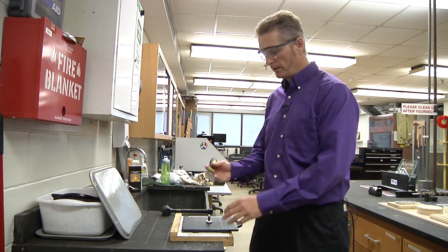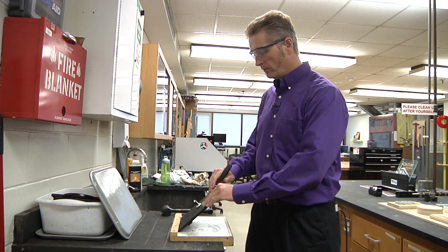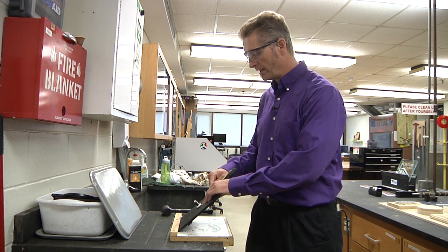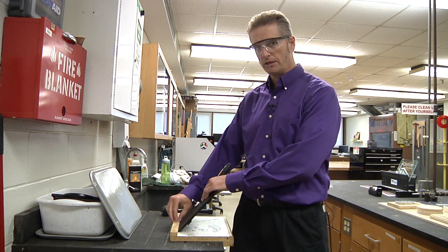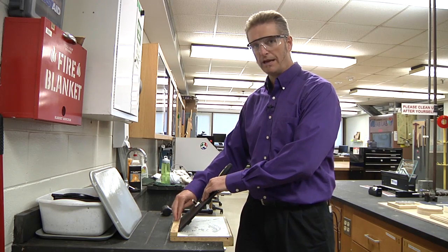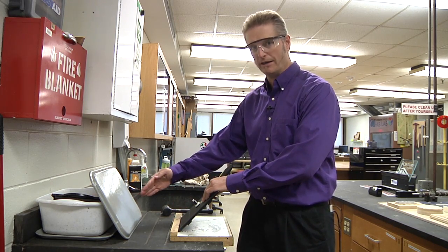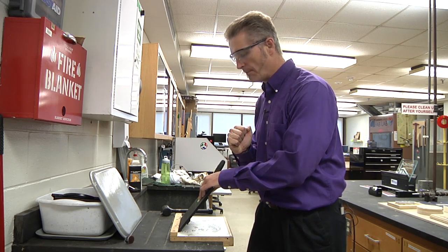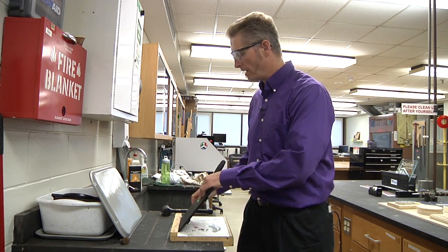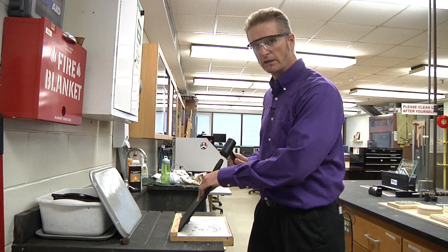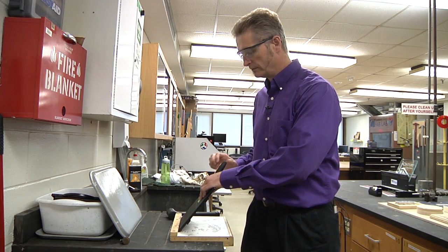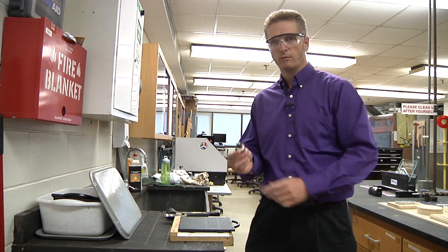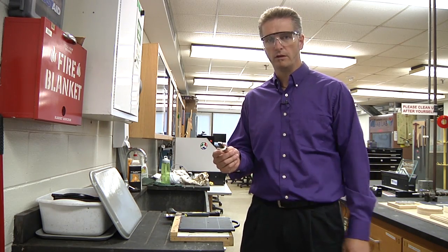We're going to take our scraper, we're going to take our tray, we'll place the scraper flat down at the base of our part on the tray. We'll hold it up at an angle and push it into our bench hook. This is going to add our support so it doesn't slide out on us. At this point, we can try to remove it by hand. You can try tapping on it. Sometimes it'll pop right off. Otherwise, we can use the mallet to give it a little extra force.